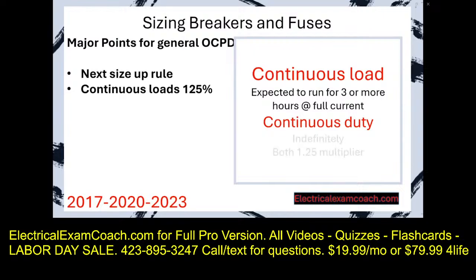You may also hear the word indefinitely. Just to try to throw you off, they might use the term indefinitely. Well, it falls under the same classification of needing a 125% multiplier. Remember, it's just another demand factor.